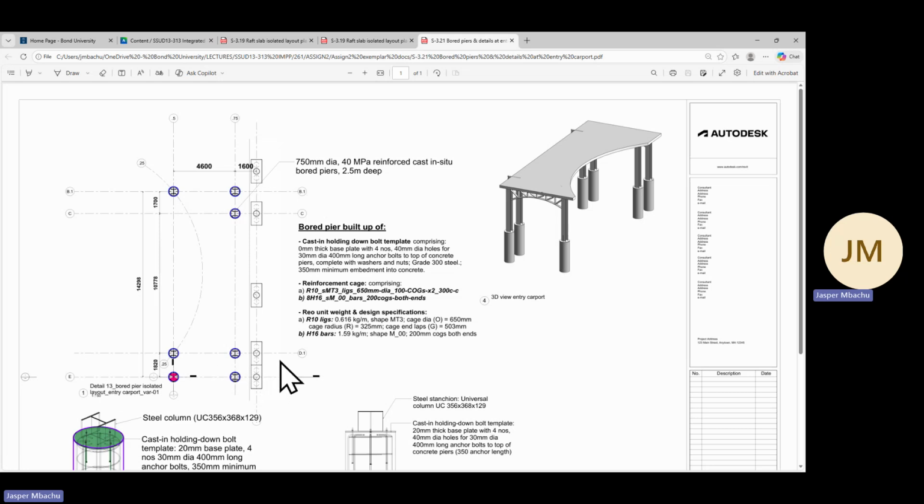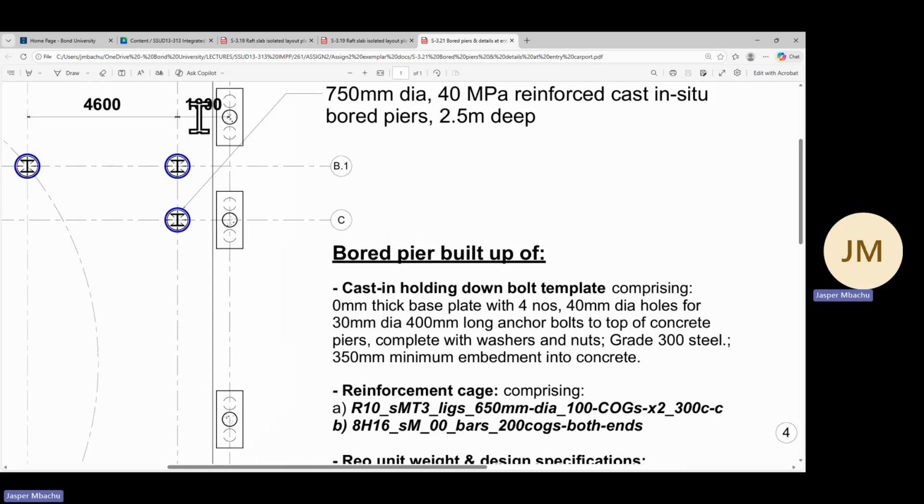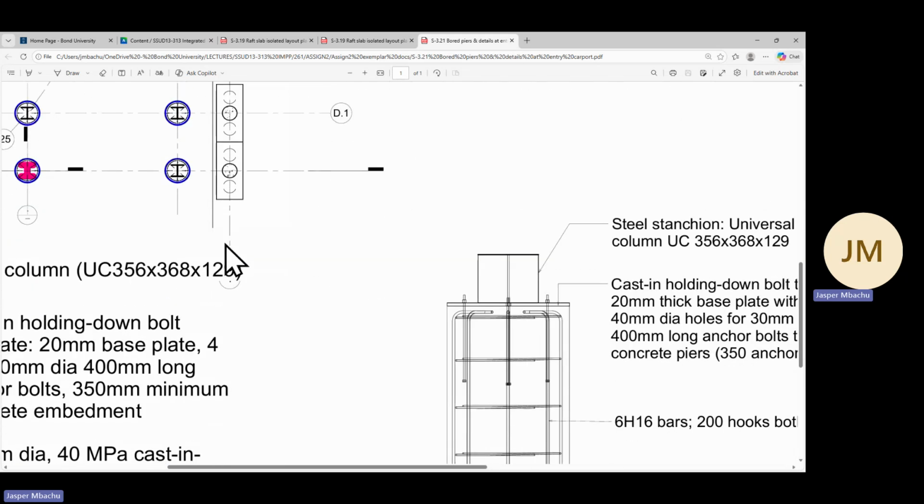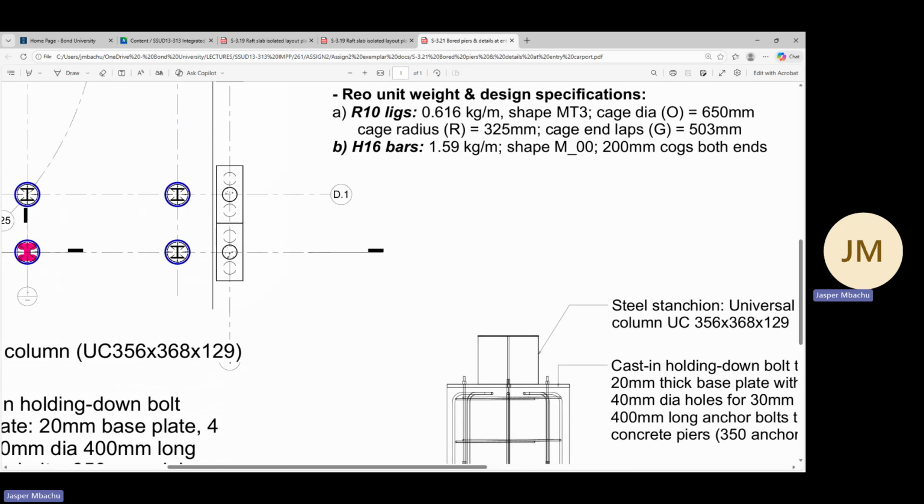And we're not interested in this part, and we're not dimensioning them, but we want to dimension between the piers and possibly give, like, from where this aligns with the other grid line. It's good to indicate that as well, because that helps in set out. So that's what we did there.